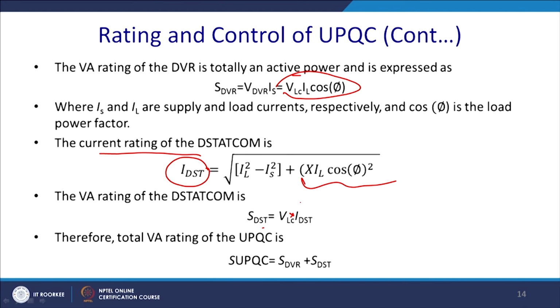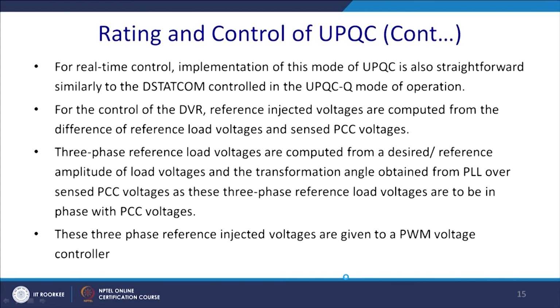Similarly, the total rating will be DVR plus D STATCOM, but generally the D STATCOM will have a higher rating than the DVR. So, what we can conclude is that the real-time control and implementation of this mode, UPQC P, is also straightforward, similar to the D STATCOM control in the UPQC Q mode of operation.